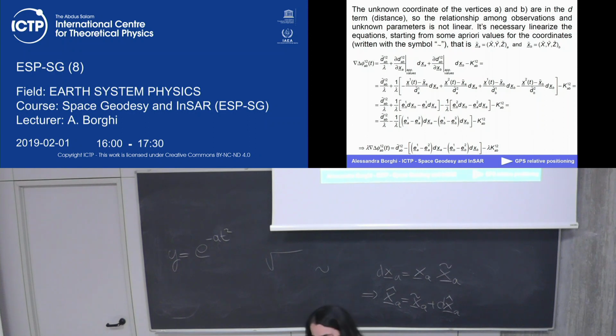I need more digits to say, for instance, my point has a latitude of so much, because I already made the measure of this benchmark, or because when I started my observation, the GPS gave me this information, but it was approximate information, because they obtained this approximation in real time using code observation, without all this huge and important analysis of data. A sort of preliminary data? Yes, approximated is like a preliminary, yes.